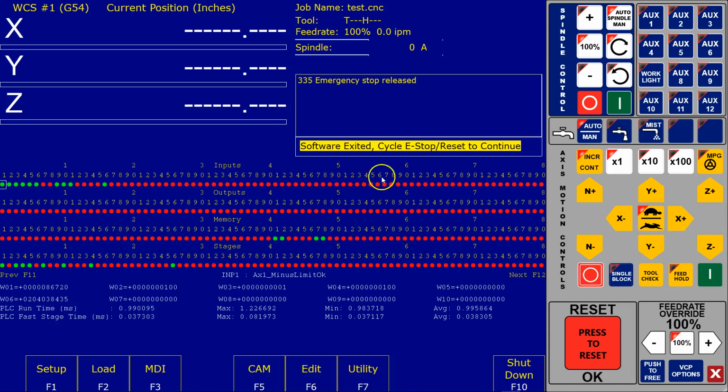Okay. As of right now, you'll see that you have either a red or a green dot. The red means false state. The green means true. Now, it does not mean open and closed because we have the ability of inverting an input. So for example, just wanted to mention that by default, all our inputs are basically viewed as normally closed. So we're looking to see that a closed input is in its true state. All right. So right now, inputs 1 through 6 are closed, 7 and 8 are open.